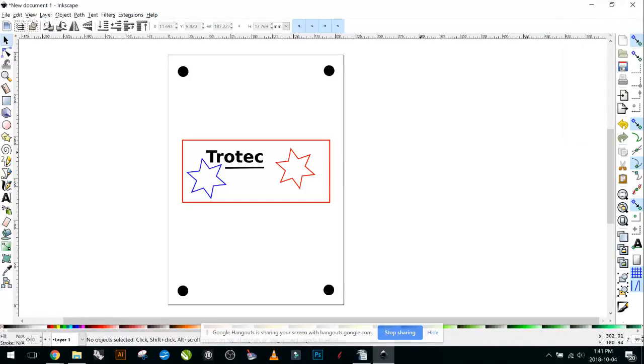Yep. Julian said that by default, trace is done with solid infill and no stroke. So to change that, you would go to Object Fill Properties, and then set the color to white, and turn on stroke color. So I can put that for you in the chat there, Anthony, in a sec.